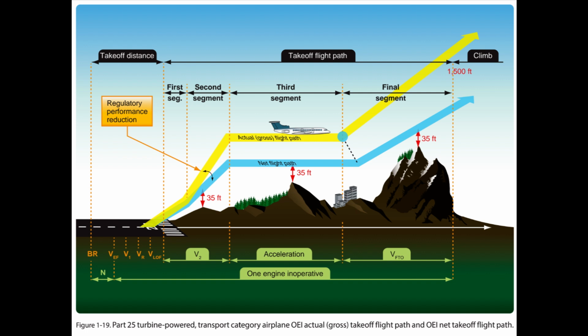These two methods of assessing obstacle clearance are necessarily quite different. TERPS is used by the procedure designer to determine a lateral path that is usable by a wide variety of aircraft types and establishes a clearance plane that aircraft must be able to stay above to fly the procedure.